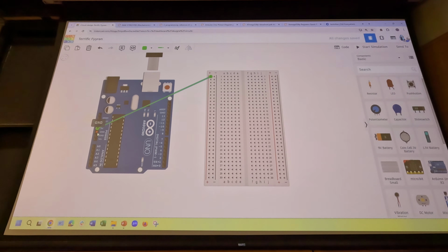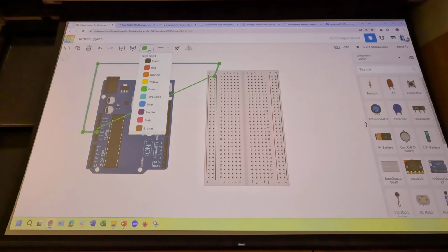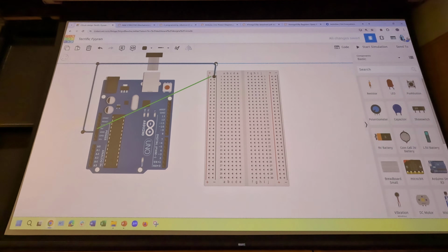So you can do that either when you start adding a wire, you can click to route it, right? And I think I showed this one back when we first used Tinkercad at the beginning of the class. And then you can change the color up here, right? And if you've already added a wire, you can click to move those points or double click to add new ones. Okay, so again, part of this is kind of personal preference and style, but come on, double click, there we go. I strongly recommend not just kind of having crisscrossing green wires everywhere, just like with a physical breadboard. As that gets messy and you add more stuff in the circuit, it's going to get harder to debug.